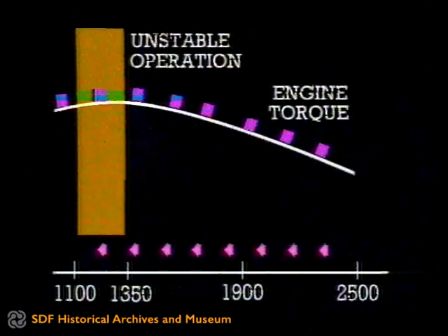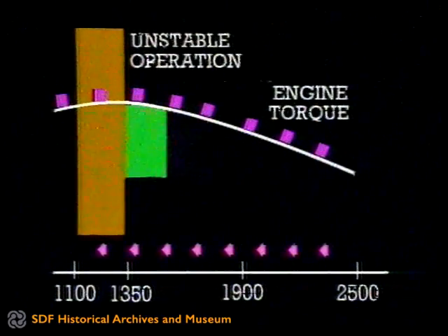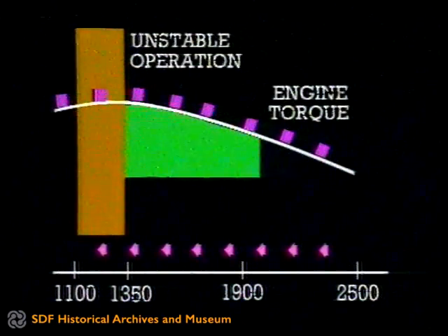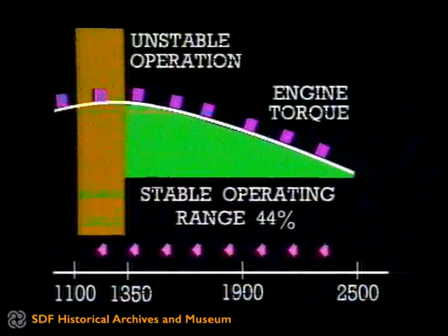For the purposes of resilience, therefore, two parameters are important. The first is the extent of the stable functioning range, which must be as broad as possible, at least 35% of the maximum output speed, and within which it is possible to operate by varying the RPM without changing down. Any engine which obliges the driver to change down at a minimum variation in RPMs is not resilient.